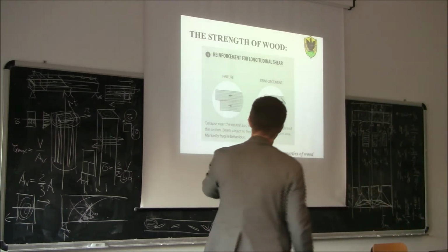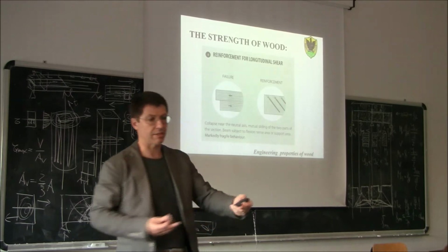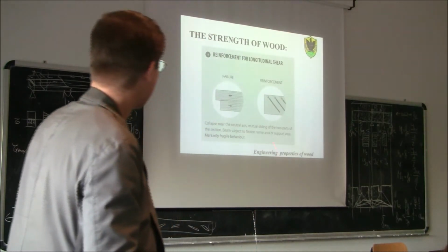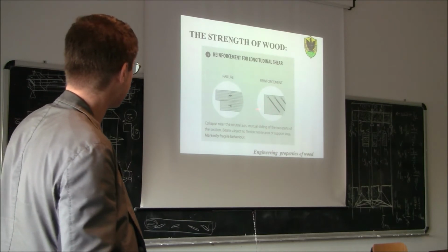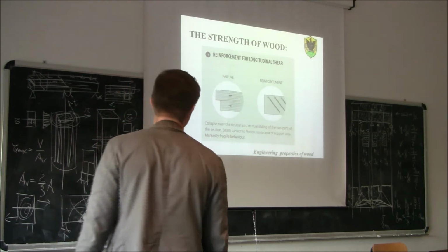You see that the screws are oriented along the tensile direction, so we orient the screws such that they can work in tension, and they can provide some shear resistance along this possible shear failure plane.